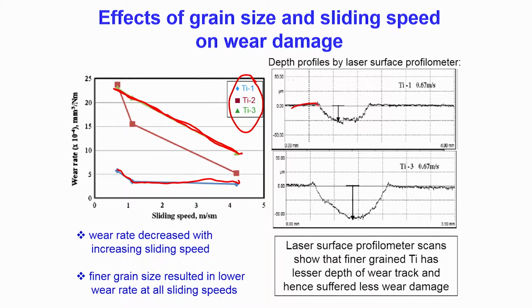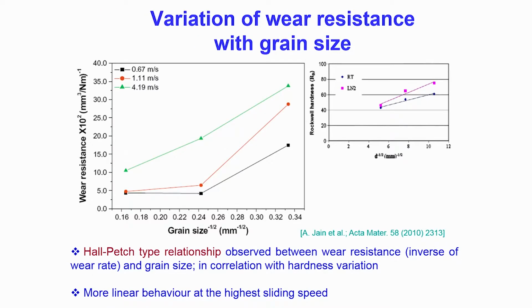And this is the 2D profile that we get from the laser surface profilometer, and the typical depth is close to 50 micron, which is very significant wear. Now, this is quite an interesting observation.